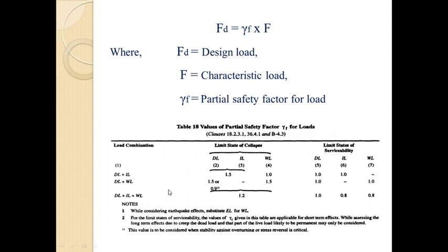Then for dead load plus wind load, it is taken as 1.5. For dead load plus live load plus wind load it is generally taken as 1.2, and for the limit state of serviceability it is nearly equal to 1, for dead load, live load or wind load also.